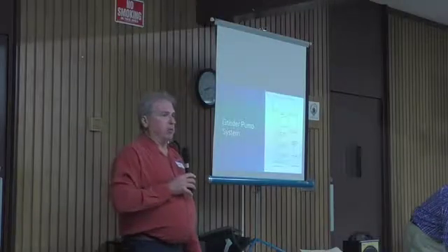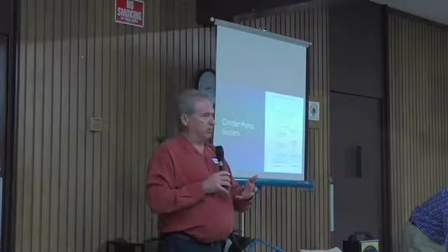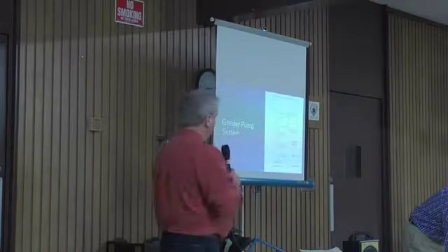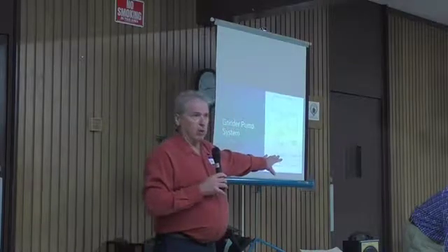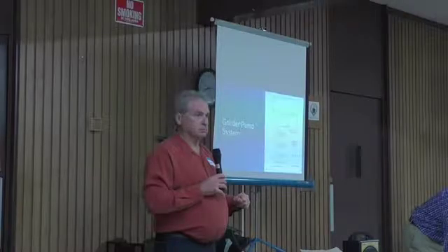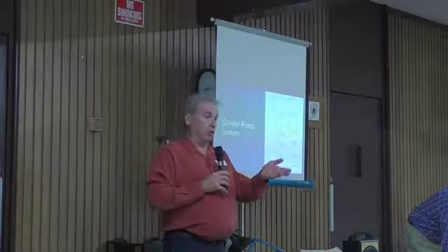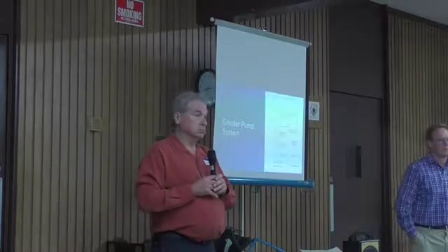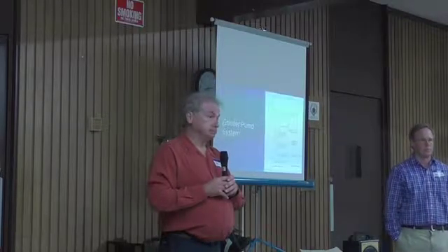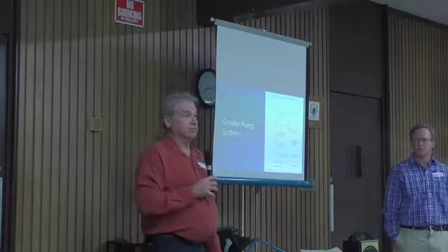I don't believe that there would be a requirement for the electrical system to be evaluated just to be able to have this grinder pump added to the home. Did you say 30 amps? Because a lot of these panels are only 30 amps to start with. But normally you have 20 amp, 30 amp, 40 amp breakers in that panel. Sure, but a lot of those panels are just ancient. So the homeowner would be on the hook for that. Yeah, there might be a problem, just like if they were adding an air conditioner to their house, they might have the same issue.